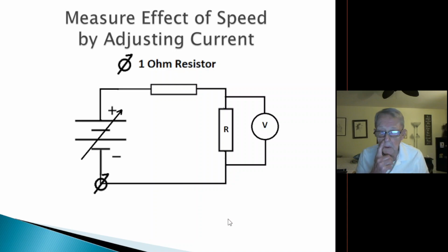The other thing I'm going to do is a test. This is a simple circuit where I'm going to get a 1 ohm resistor, place it here, and measure the voltage across this. If I know the 4-wire resistance of this 1 ohm resistor, when I measure the voltage across it, I'll know the current. I'll use a voltmeter to measure the resistance. So I have the current based on a 4-wire measurement, and the voltage on the 2-wire measurements. I divide the voltage by the current, I get the resistance, and I'm hoping I'm going to get a more accurate resistor value no matter what the resistor is.